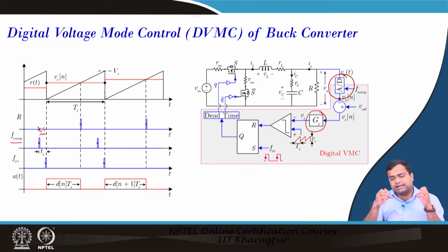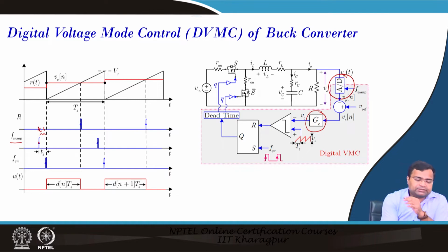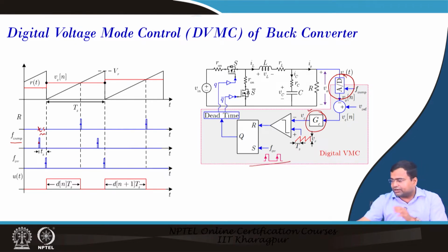We will discuss how to insert such delay in the MATLAB model, so that we can sample fast and then switch, because after taking the sample, the controller voltage, which is the output of this controller, will be ready after a certain amount of delay, and when it is ready, we will start the PWM switching operation, and that is driven by a trailing edge modulator.